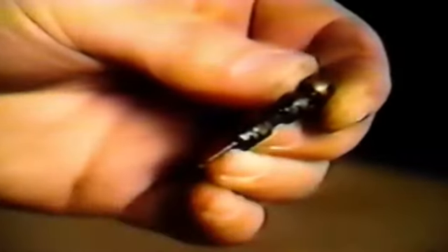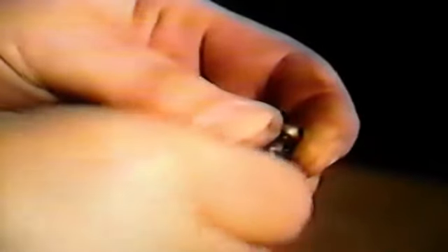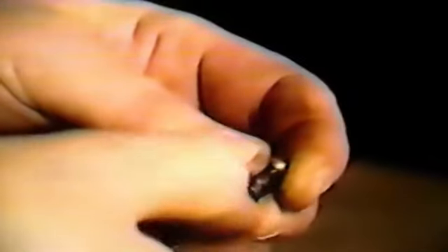It's also important to note that these are not your standard O-rings. They are metric O-rings. And while you can't find them in your standard O-ring assortment, they do come in carburetor kits or can be purchased in individual packages of 2 rings. And remember, you cannot replace metric O-rings with standard O-rings. They must be of the same type.